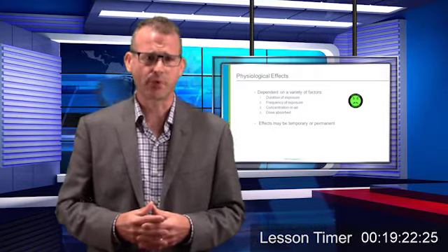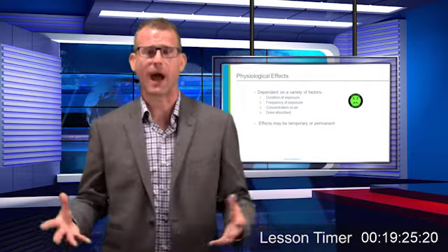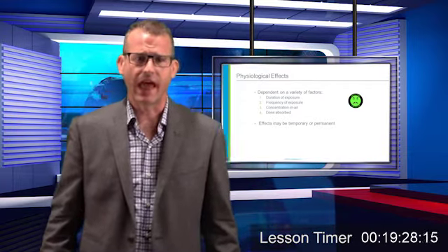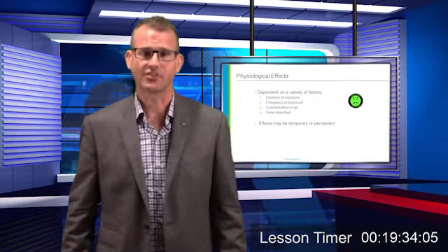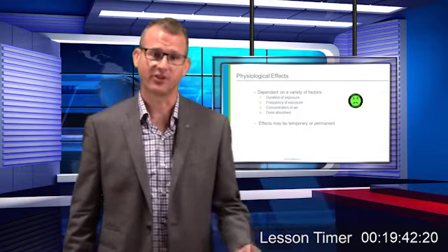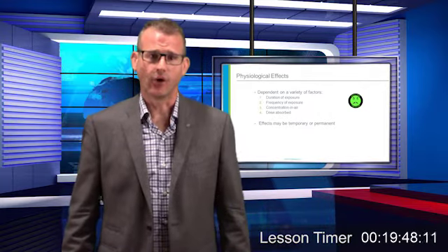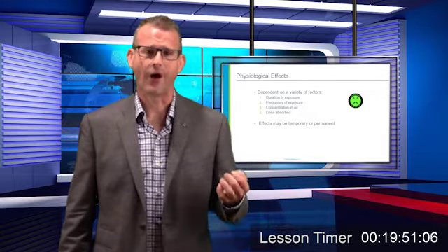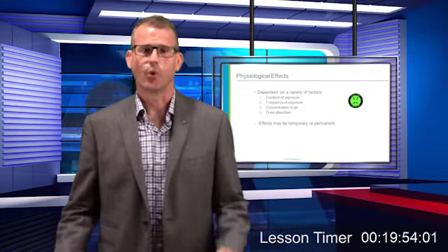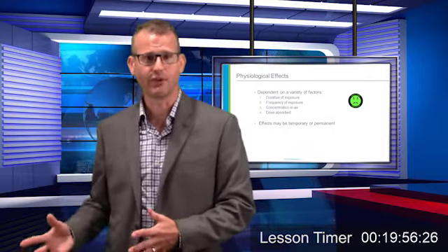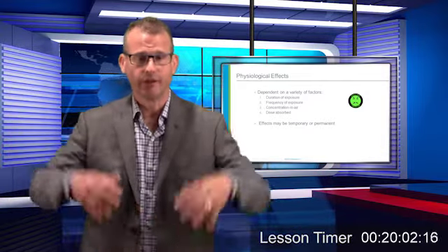These health effects may be temporary and go away once the exposure to the compound has stopped, or in some cases we can have long-lasting impacts like causing tissue damage or genetic mutations, or even causing some form of occupational cancer. There will be varying levels of severity depending on the hazards associated with this particular API. So it's also important to understand not only the hazards of the API, but equally important how the containment system is planned to be used. What types of processing will be done, how many people will be using it, the size and dimensions of these people, the weights of the material being handled, the list goes on.